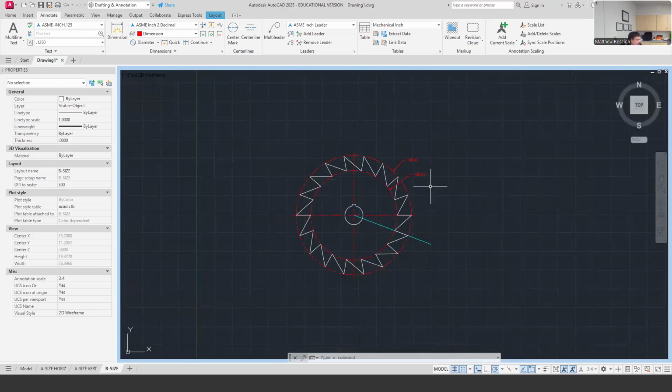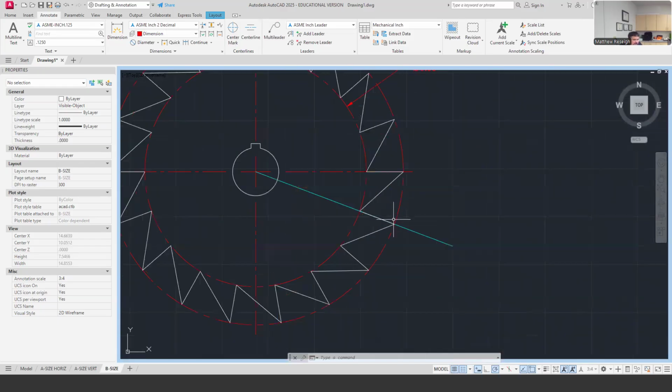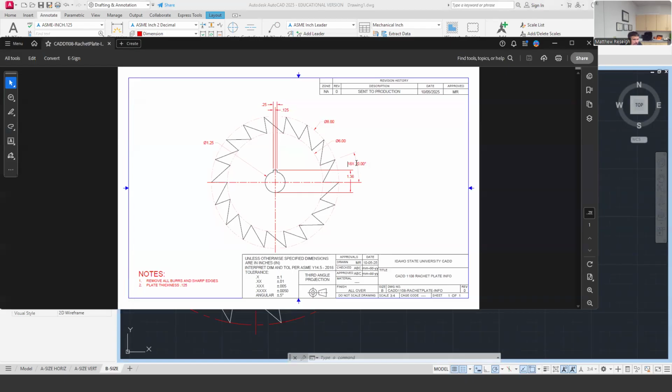And then I'm going to need to know that 20 degrees, it was pretty critical. And I think if I do that, I could turn this one into a center line as well. One thing that I may add is where this is referencing 20 degrees, to make this just a little more clear. This kind of breaks away from that a ways. I think I'm going to turn my construction line into a center line and let it extend past here a 1/4 inch.